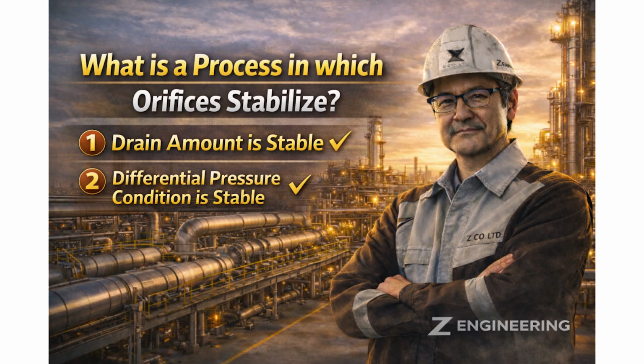Let me start with the conclusion. There are two key conditions. Steam consumption must be stable, and differential pressure must also be stable, or even if they change, the change must stay within a predictable design range. That is the basic requirement. Now, let us look at several examples.